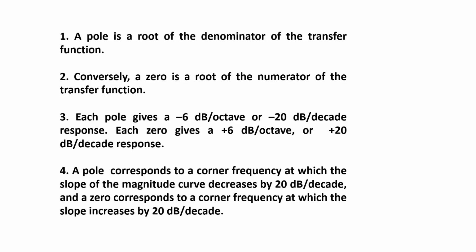So that's how you will be able to understand the magnitude response and further the phase response by introducing a zero or a pole in the system. All right. Because the poles and zeros will actually determine the roll off of the filters, whether the filter is a low pass filter, high pass filter, band pass, or band stop, those will be determined by the coefficients of the filter.